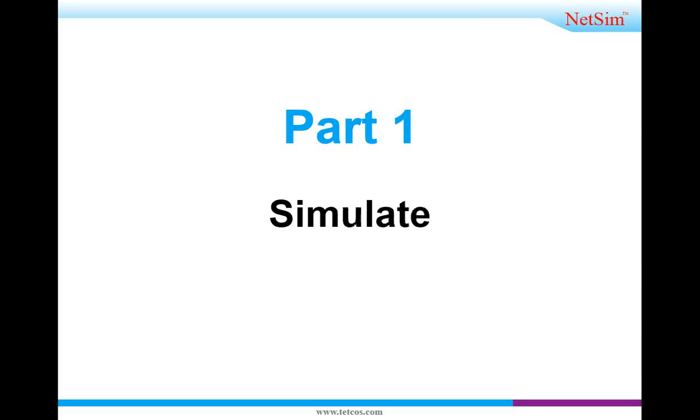After modeling the traffic, you have to simulate. In simulation, you have to give the timing of the simulation, whatever time you want to run the simulation, and you have some options for setting the recording and running of the animation. So that has to be set while doing simulation.